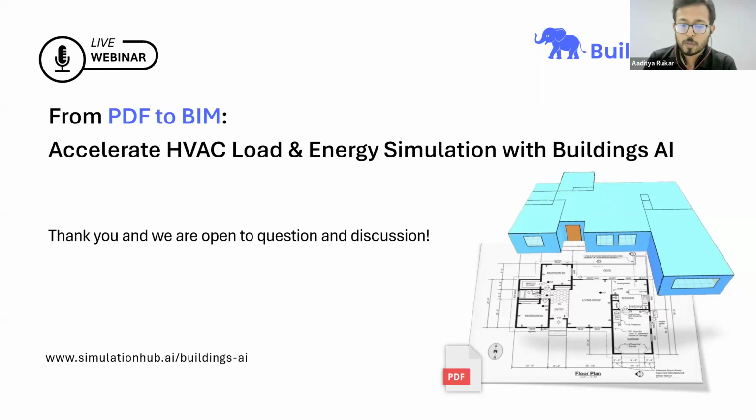That's why we included this FloorSpaceJS stage, so that you can edit the input which was generated through AI. As you all know, it is 70% accurate, so you can edit anytime. And it reduces your time in comparison with trace-over.